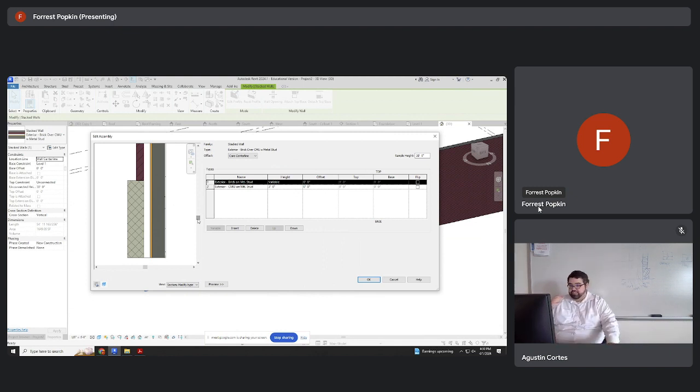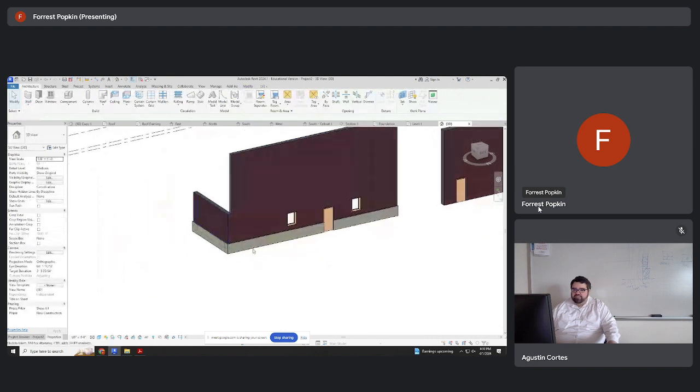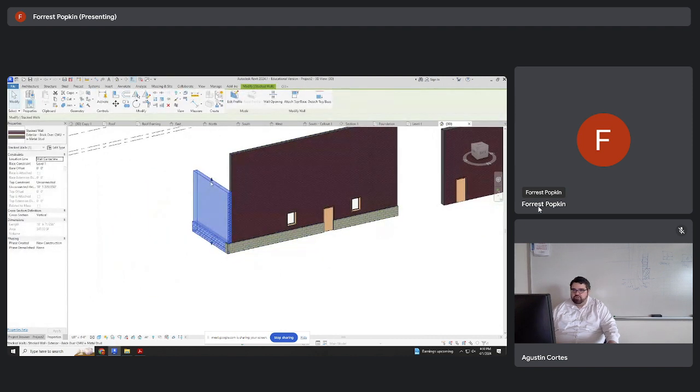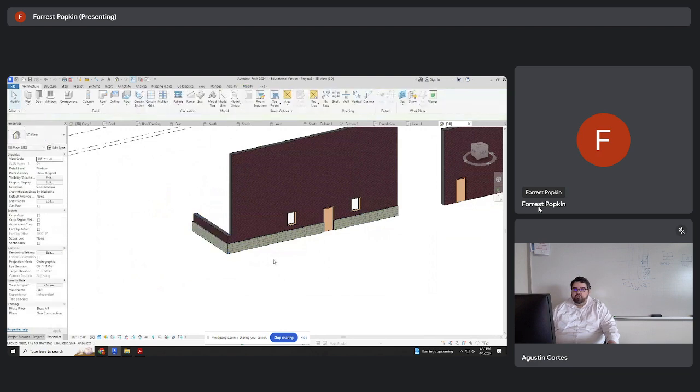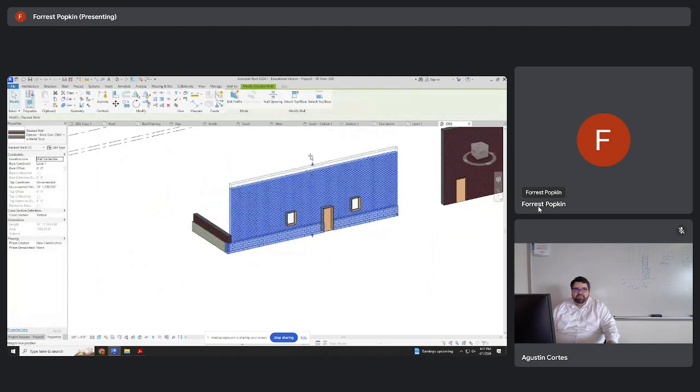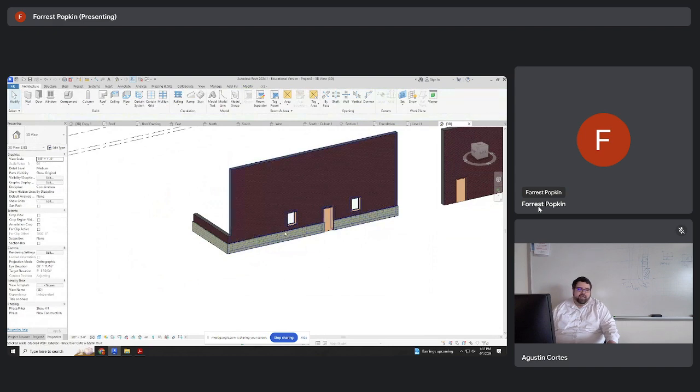Okay, after that quick lesson, you'll see here we have exterior wall, brick on metal stud. That's the guy on the top. Then you have CMU on metal stud. That's the guy on the bottom. And you'll see it says height. For the one, it's variable. That makes sense. Let's exit out of this for a second. It's variable because if I were to make this taller or larger, or smaller or shorter, I have a variable amount of brick at any given time. What's not variable is my base. In fact, that's partially why I have a base, is so it kind of keeps it level, right?